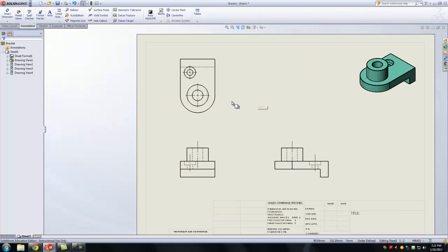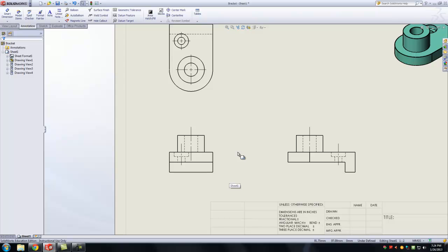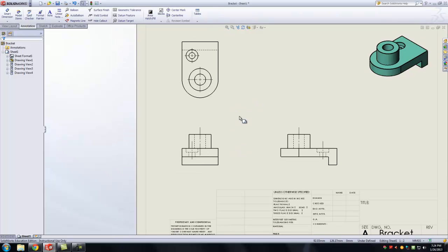So if we look over here, what view is this? But if we're talking in terms of cylinders or hole cuts, is this the rectangular view or circular view? Circular view, right? So this is the rectangular view. So technically, if this is a cylinder, I need to dimension it in my rectangular view, correct? All right. So remember we talked also how we measure from one edge. So try as much as possible to group everything from one edge. So here's how we can do this.